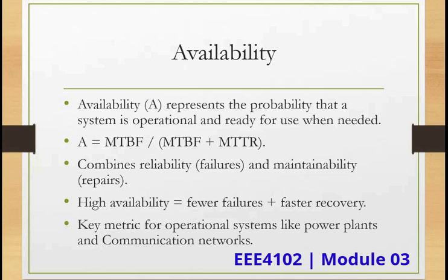The availability increases. Why? Because when we reduce MTTR, even if we don't change the MTBF, since it's a fraction, our denominator is going to decrease, and that increases our availability. Great. At least someone is following.